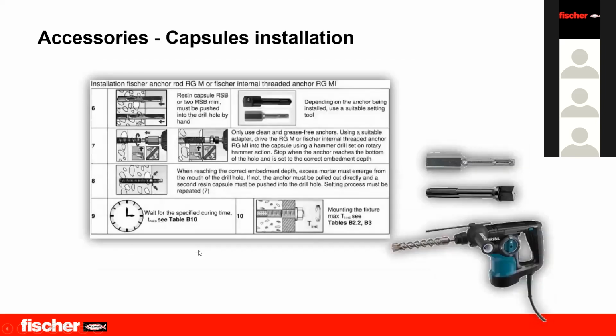For capsule installation, you have its own accessories so that the capsule breaks and is fixed properly. It will have a chisel, and a sharpened rod is used so that the capsule breaks inside the hole and the rod gets installed properly.